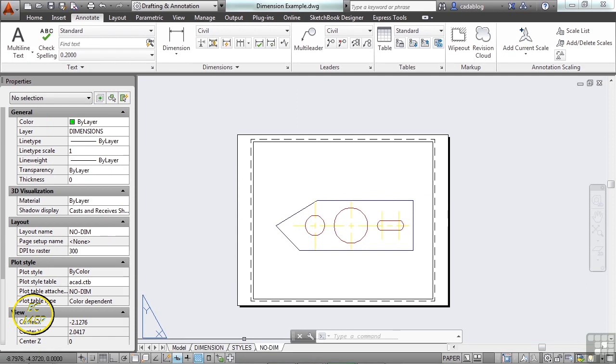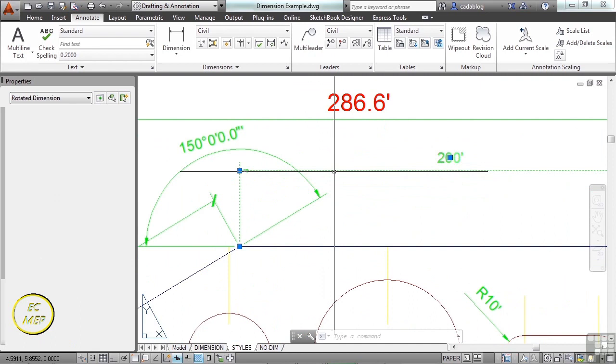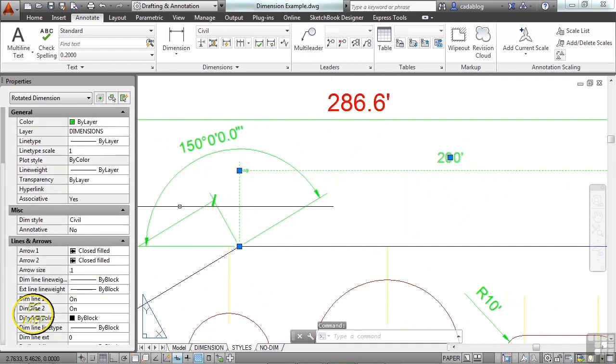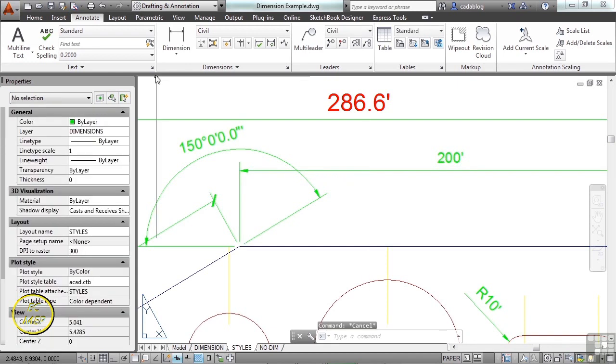Now go over to the Styles tab. This dimension style uses a text style for the text. The text style it's using is called Standard. Now we have 4 different styles in this drawing. They all look a little bit different, or are different in some way. Different size, different color. It could be a lot of different ways or reasons that you would want to make a different text style. Your text styles can be edited right here.